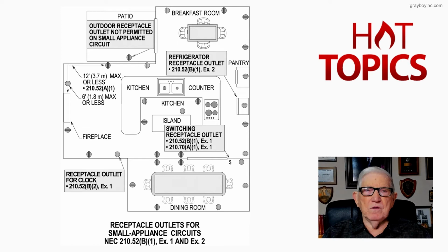So if you multiply 800 by 2, that's 1,600 square foot. And you say the area that you look at in this illustration, figure 10-12, if you exceed that 1,600 square foot, you need to bring in another circuit by the code. But you may have to have more circuits than just 2 by city ordinance or state or county type ordinance, or the builder wants more because the person that's having the home built maybe wants more small appliance circuits. So this is typically how we deal with the small appliance circuits, and that's what this figure 10-12 is illustrating to the user of the NEC.